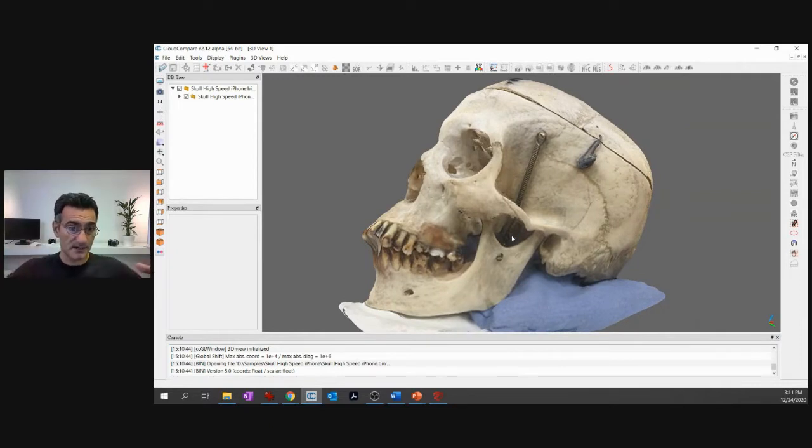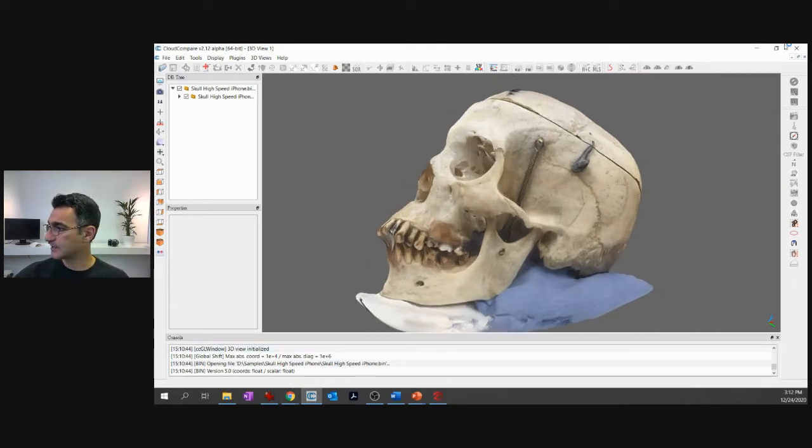It saved me from taking a lot of photos, and in a 20 or 30-second video, you can capture a lot of overlapping images. And that's the benefit of video. Because you're recording at a higher frame rate, this one might have been at about 120 frames per second or so, I have a lot of overlapping images. So there's no chance that I'll capture one side and then just the other side with nothing in between. There's always going to be this gradual transition from one area to the other. So having lots of overlap is going to be super, super helpful. And yeah, that's kind of what it looks like there.